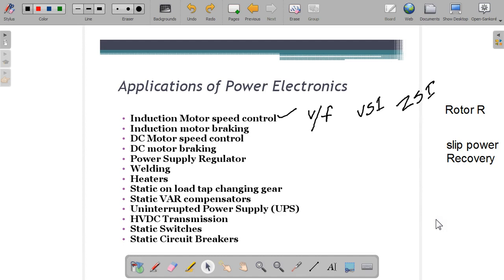As in rotor resistance control drive, the efficiency is low as slip power is dissipated in the external resistance. This is more drastic at low speed or high slip value. Closed loop systems, namely speed control and current loop, are usually used for better control and current protection purposes.